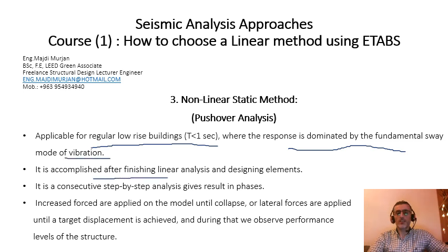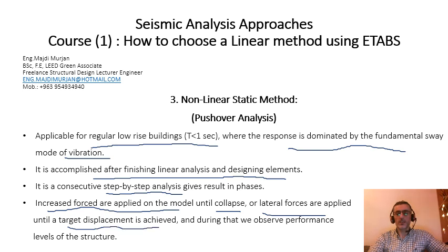It is accomplished after finishing the linear method and designing elements, by step-by-step analysis. Now, the concept is that increasing forces are applied on the model until collapse, or lateral forces are applied until a target displacement is achieved, and during that we observe the performance levels of the structure.